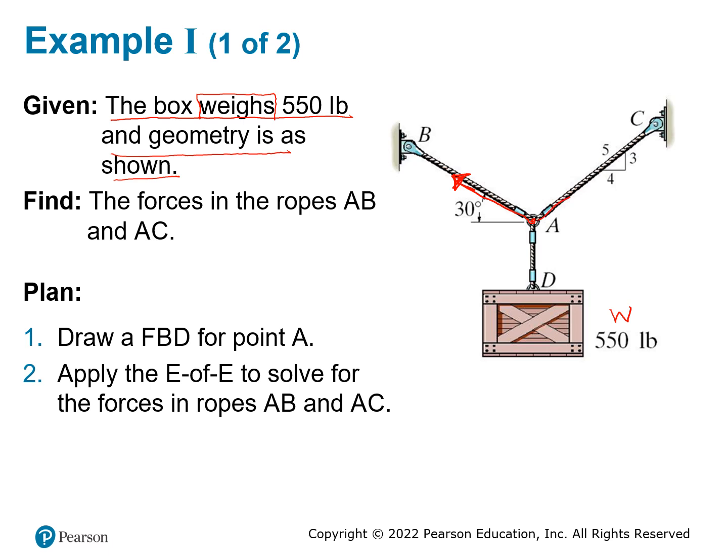AC is going to be the force here, and also this is a tension force, so outward of this connection point A. What about the force going down? This is another cable, and we know this force is going to be equal to the weight, because we just showed you in the previous example. This force is the weight of this box at the bottom.